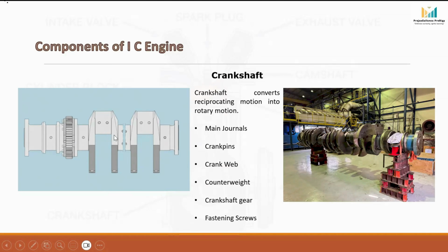The crankshaft is not a solid piece of metal. In reality, specially drilled oil passages are provided inside the crankshaft for lubrication purposes. These oil holes play a very important role in supplying lube oil to the rotating bearings. The lube oil pump sends pressurized oil to main bearings mounted inside the engine block. From the main bearings, the oil enters the crankshaft through oil holes provided in the main journals. The oil then travels through internal drilled passages inside the crankshaft and reaches the crank pins.